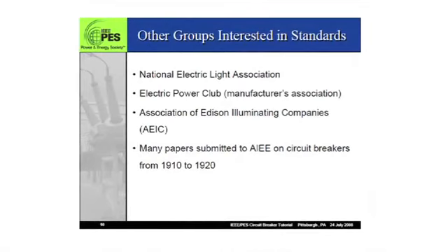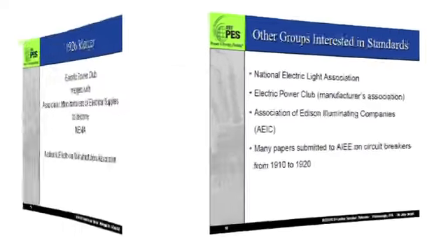I mean, these are some of the slides. 1919, there was a club formed in electric power. And in that club, they decided that the breaker must be able to make two open operations with two minute intervals. No limit on flame or oil rejected. Doesn't matter. I mean, it can burn as long as it interrupts twice. Beautiful. I love it. Just interrupt. I mean, this is how far we went with the technology. It's amazing. Now we have 100 short circuit interruptions and people complain it's not enough.